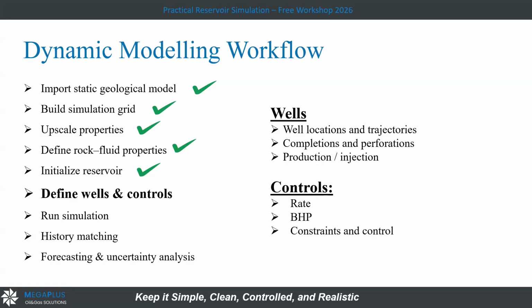You have to insert all the well models in the right location, and then something called control. When you produce the wells in the simulation, you have to control each well, like in reality, where you can control it by choking, or switching on and switching off, anything. So in the model, it's the same thing.